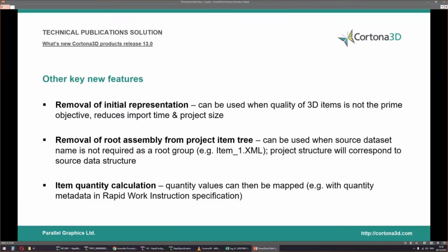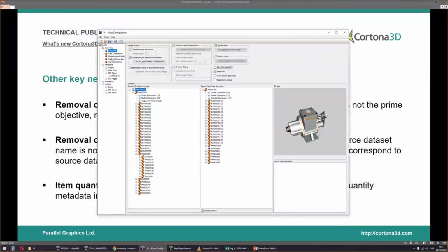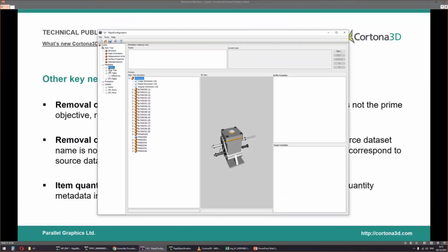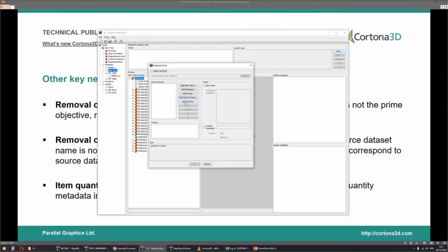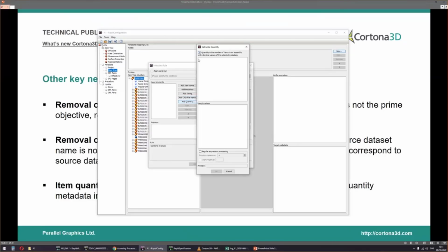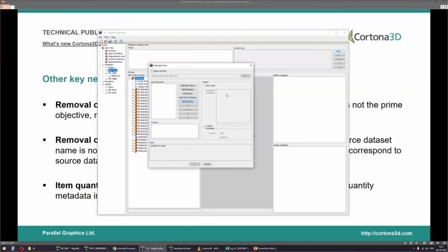As previously, you could only either fetch quantities from the CAD file itself or use some programming in the input profile directly. But now there is a handy item calculation feature which we can find over here at quantity, like so. And here we would typically select some kind of metadata which is used to identify identical values and then map it with our metadata.